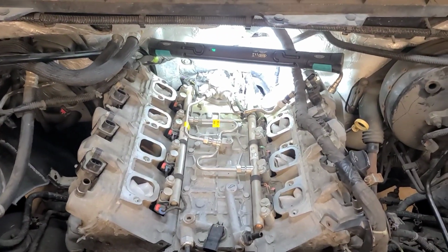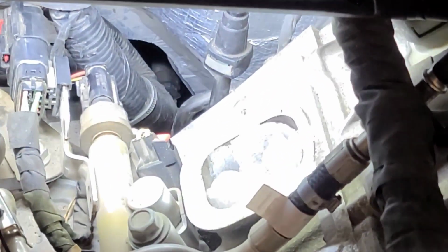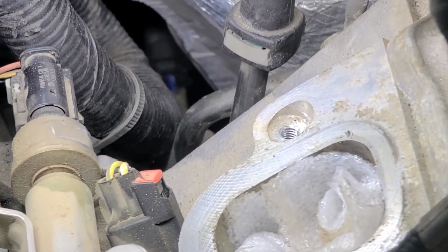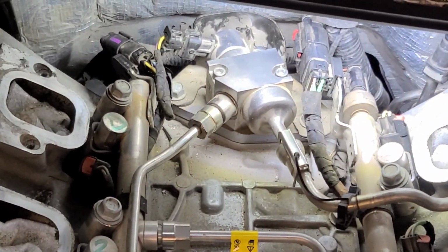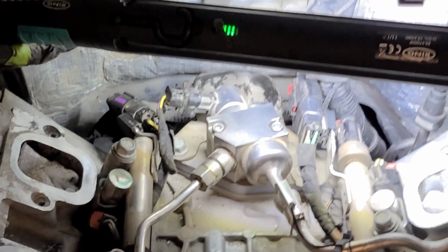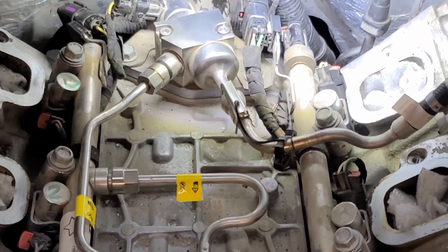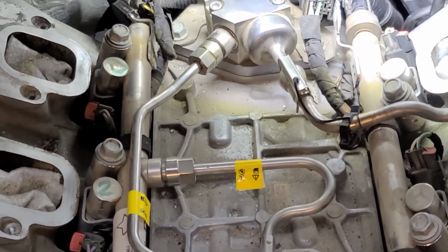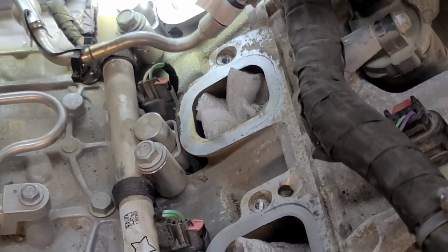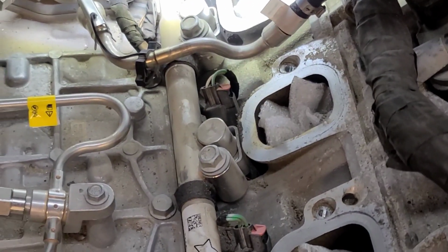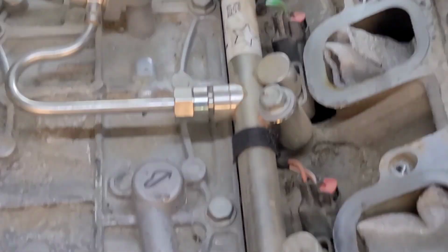So I managed to get those 2 bolts and 2 studs. They are right down below that harness on that side and directly below the high pressure fuel pump, in the middle, or just to the left of the high pressure fuel pump. Ground's connected to the back of the cylinder head on both sides. Brackets bolted up, clips attached, and ready to put the intake manifold back on.